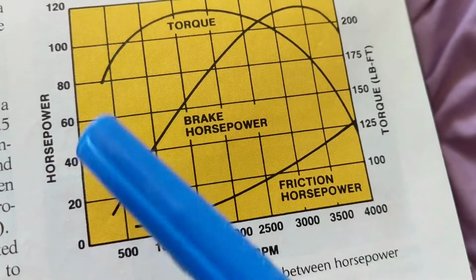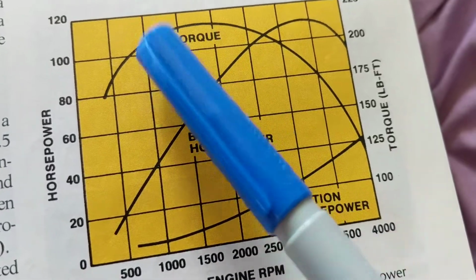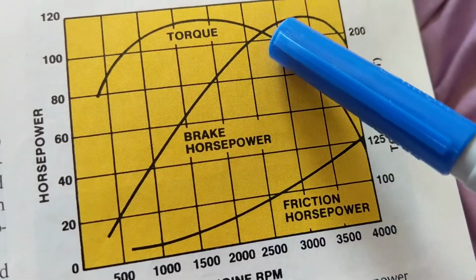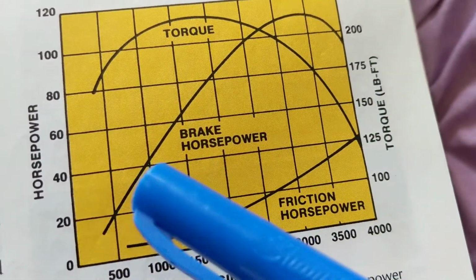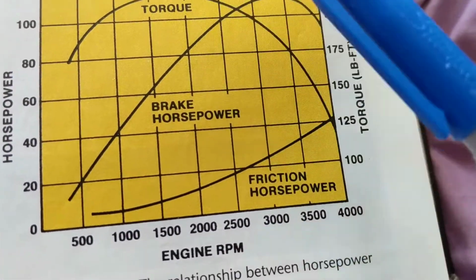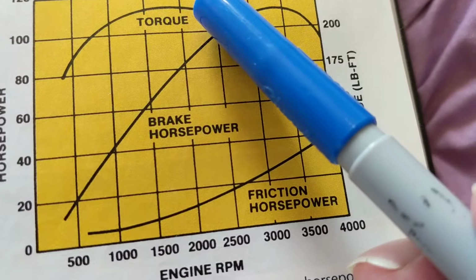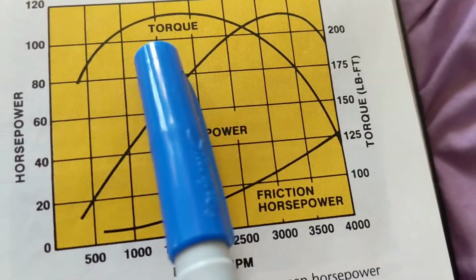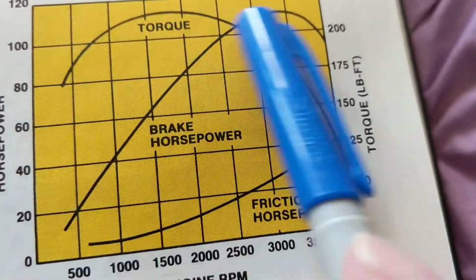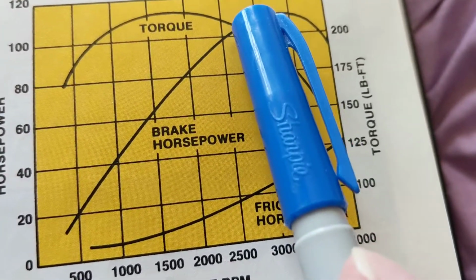Torque goes up over here in foot-pounds, right? In between 100 and 120, whatever. Guess what? Look where it bottoms out. You're already at about 2,700 when the torque already starts bottoming out. So in the beginning, when you're starting to accelerate, torque goes up. You need that torque. But then eventually at cruising speed or 2,500, 2,700, you don't need that much torque. So the torque just bottoms out. The torque is not going to increase while the horsepower is increasing, 4,000, 5,000 with it. There's a bottoming out stage. That's what this is. And this is the point that they meet.